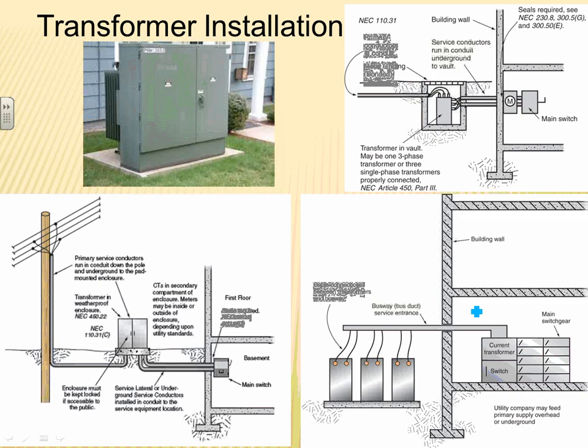What happened, guys, for us as engineers, when we do our load calculation, which we did two load calculations the first time I was here, when we oversize things. We do a lot of oversizing. So a building like this, or any building, you size a 4,000 amp switchgear, and when everything is up and running, you're lucky if you can get a load on it 40% of what you designed for. So utilities are smarter than us, because they have actual data. We based it on best practices in the NEC code book. They base their design on actual data that they pull out of every building.